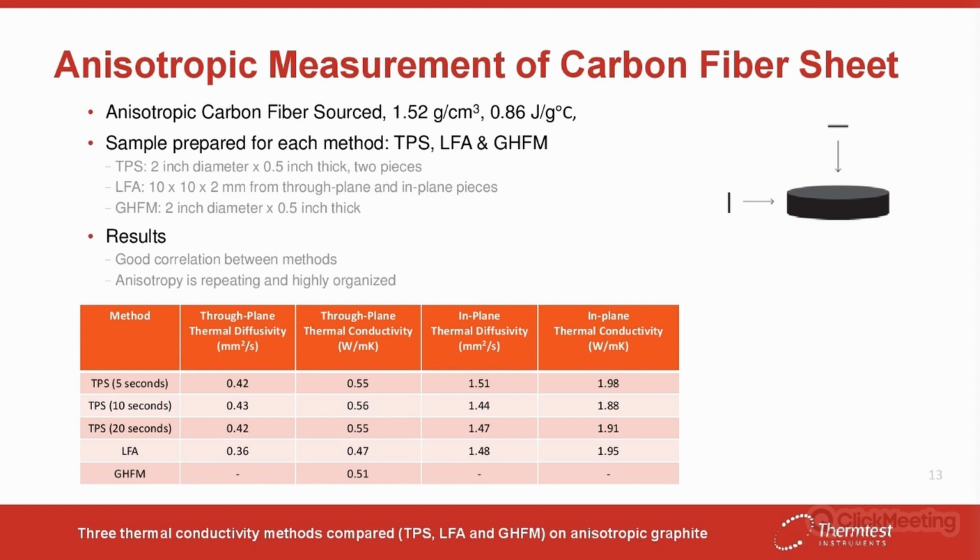So it's really important to understand that concept, that if you have layers or non-repeating anisotropy, the true value of that sample is based off the entire thickness. That's the only way to truly consider it. Otherwise, you have some number that is representative of some portion of the material's thickness, but not the full thickness.